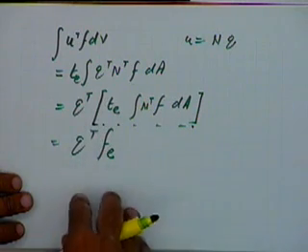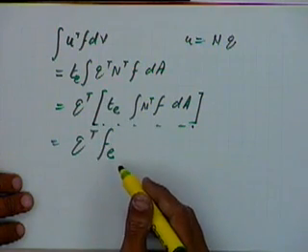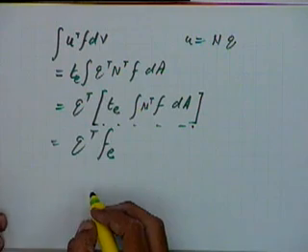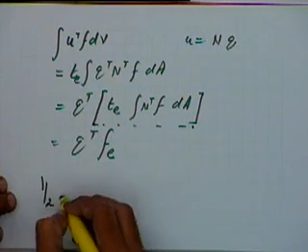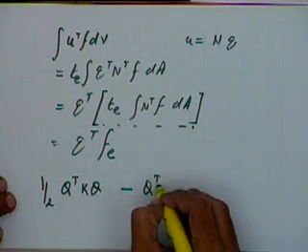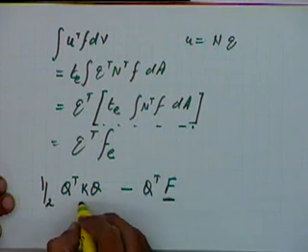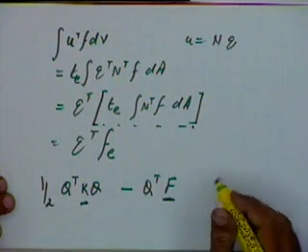Similarly, the traction force will also have to be split into the 4 nodes by carrying out an integral. Eventually we will combine all these to get an equation of the form half of Q transpose KQ minus Q transpose F. But the process of finding out this F and this K will involve numerical techniques. We will have to solve complex integrals. Any questions up to this point?